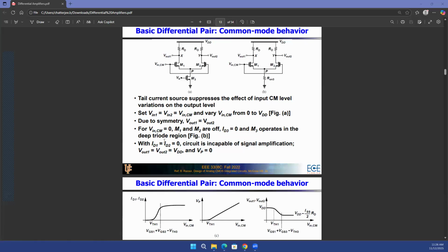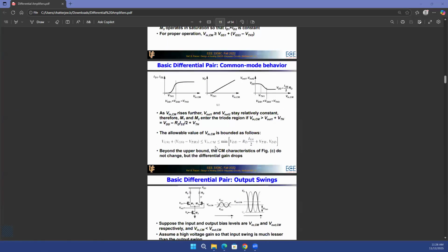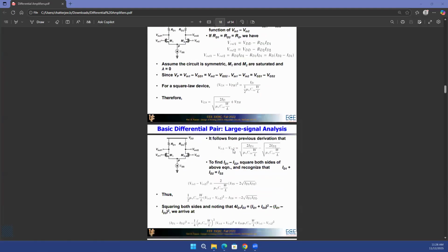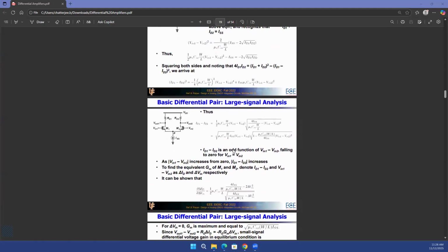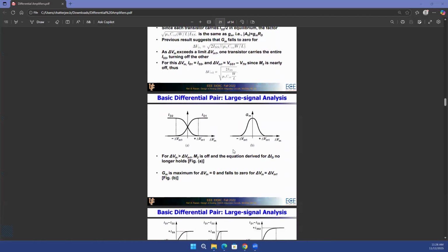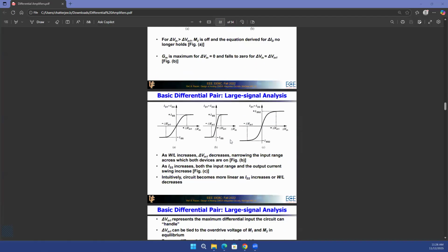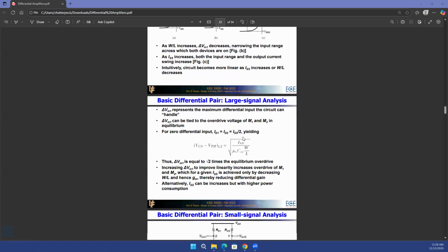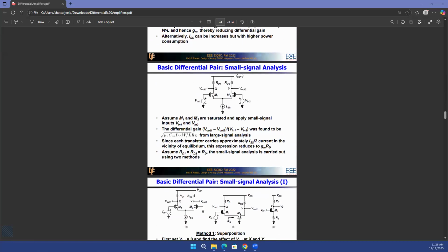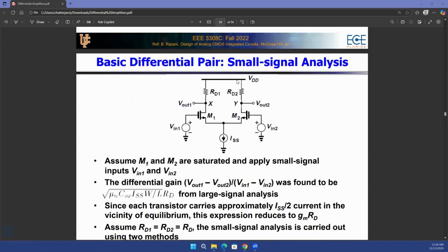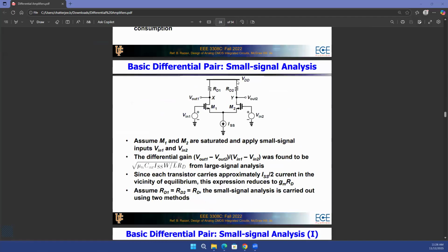All right. So that's all there in the next few slides, which is actually talking about how you make sure that the transistors are in saturation. But it's easier to understand that from a problem. So we'll look into that when we actually solve the op-amp design problem next week. But before we go there, we need to also understand how to find out the gain of the MOSFET. Right? Finding out the DC voltages and making sure that the transistor is in saturation, that's the easy part.